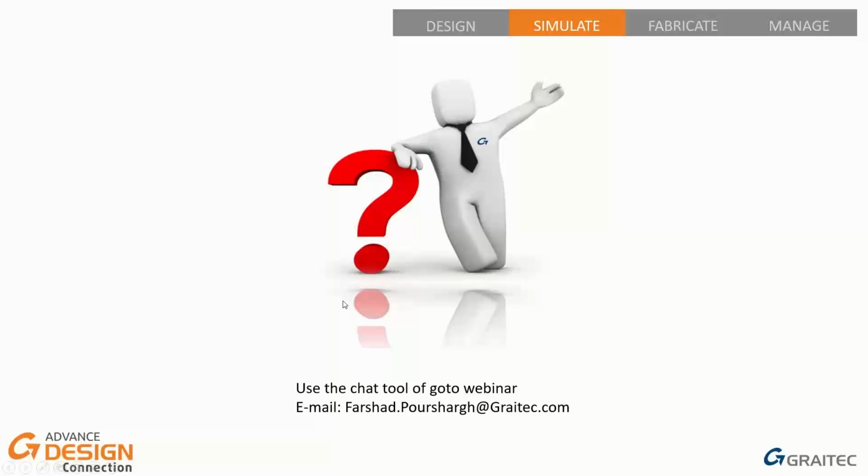Can you tell us how to add forces? Yes, I also mentioned it in the other webinar. You have several ways. First of all, you can do it manually directly in Advanced Design Connection, where we have a table to add your forces manually. You can import forces from an Excel spreadsheet. And the other way, as I showed in this webinar, is the option called import connection, which lets you import the internal forces for the connection directly from other software. Today I showed you the import from Advanced Design, but if you have other types of frame analysis software, we have special links to import your forces from those as well.